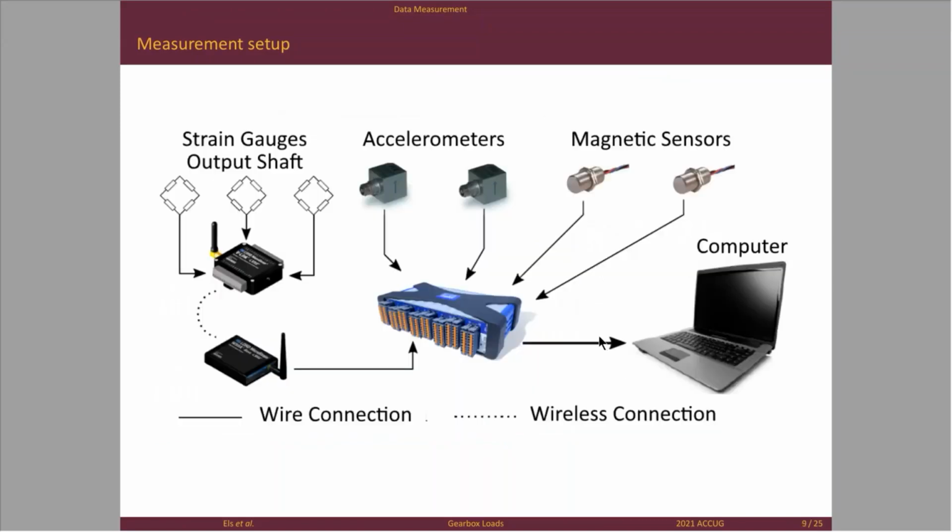The setup was basically a radio frequency transfer from the rotating hub for the 3 strain gauge pairs. And then we had some accelerometers on the gearbox and the motor to look at relative motion between the two. It is not included in this presentation. This is something that we're still looking at. Then we had some QuantumX data gathering, and then out to the computer where the number crunching is performed.